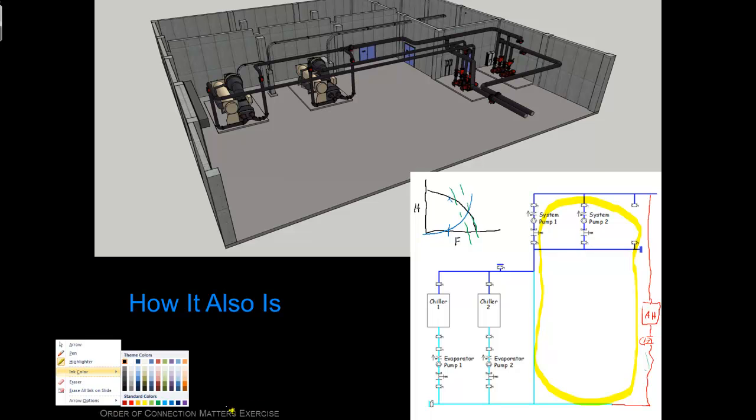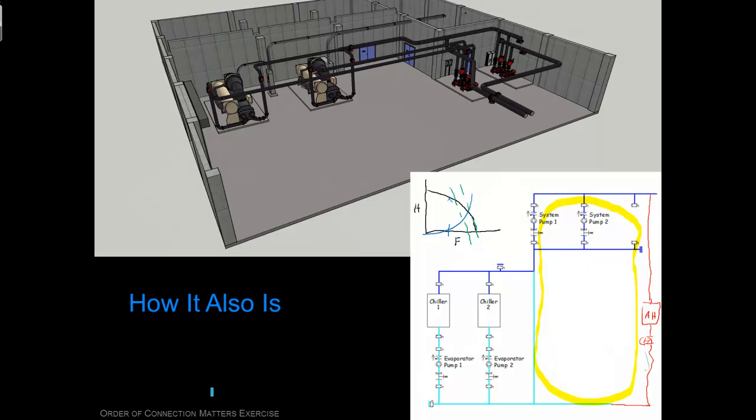The other loop that we have in the system, if you were to turn those pumps off and then turn these pumps on, water would, generally speaking, go around in a circle like that. Technically a little bit of it would go this way, unless that valve was closed. But this piece of pipe is physically very short and very large relative to the flow rate, so most of the water is going to go around in a circle like that.